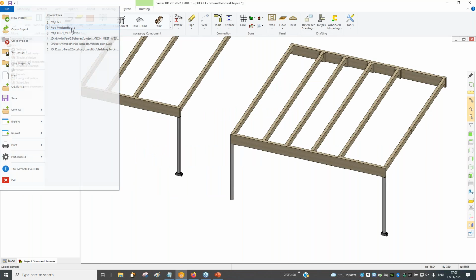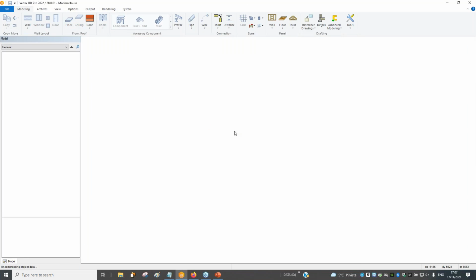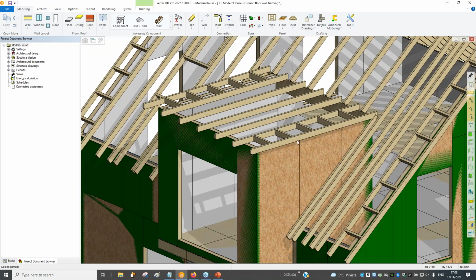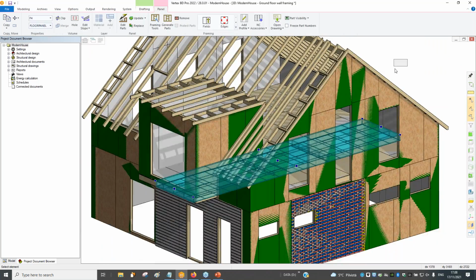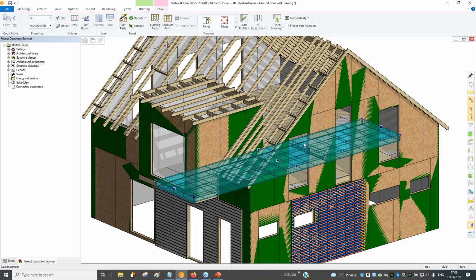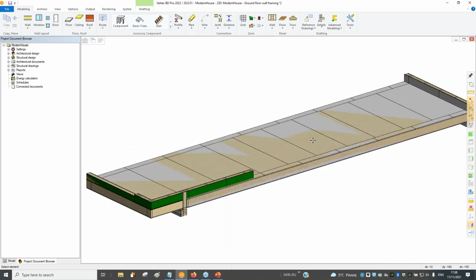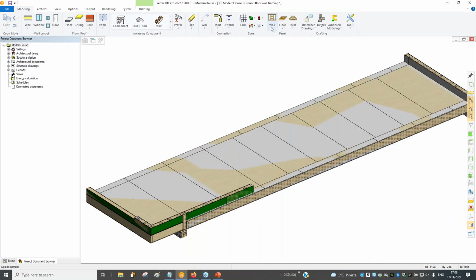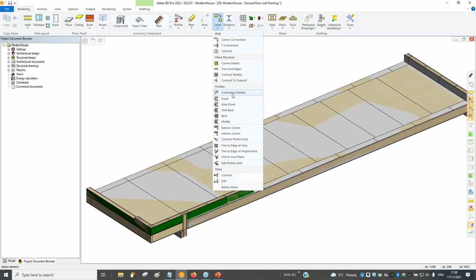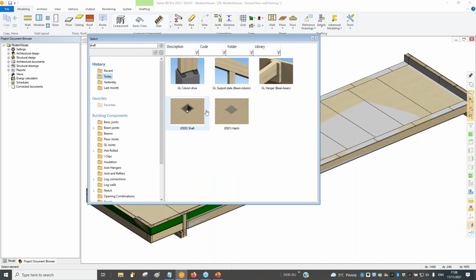There's a difference. When you make a hole, then it's just a hole. You don't have control over whether it punches through the structure or not, and there is no possibility to control that. The hatch tool, for example, cuts the sheathing area by the hole, but it also adds sheathing inside or on top of the hole as well.